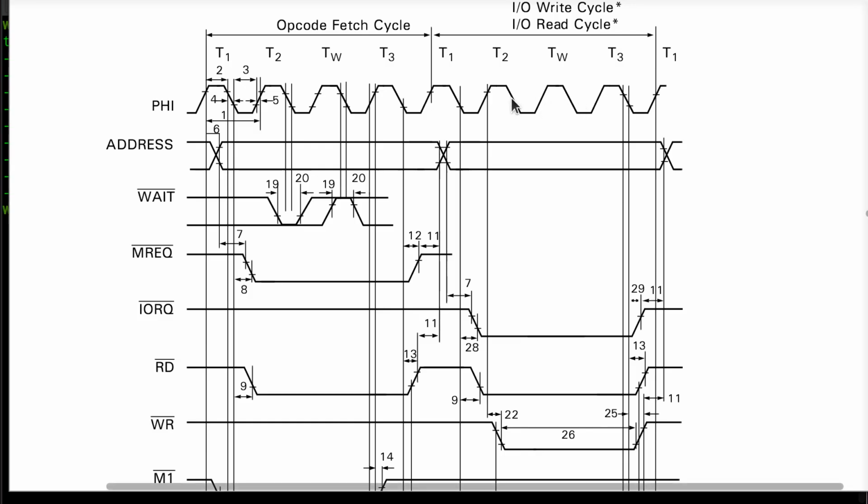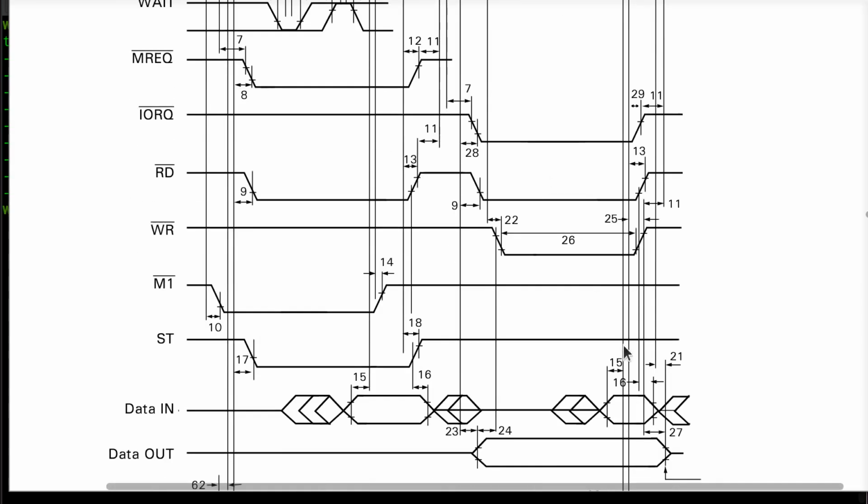The earlier I can get the data out there, the longer the FPGA has to drive that data bus and to overcome any parasitic capacitance and things like that that may cause a really low slew rate. The rise time or fall time on the signal might take a long time, because this is the time after it is stable.